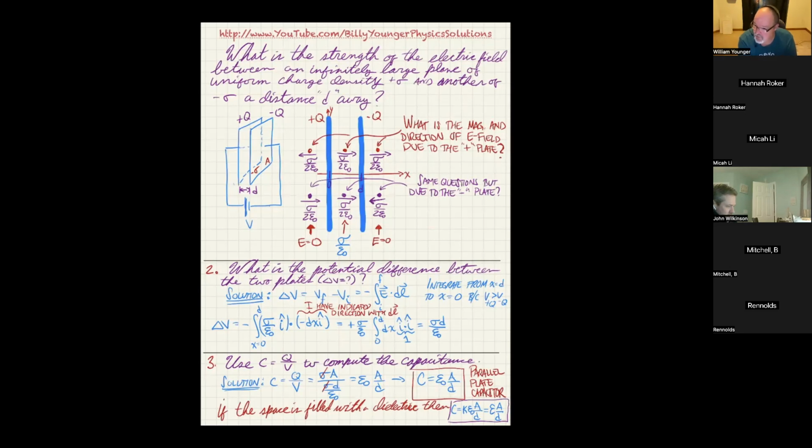Not only that, you've given it a structure where you can keep the two conductive plates from touching, because since you can see that the capacitance is epsilon 0 A over D, you really want the A to be large to get a large capacitance, and you want the D to be small to get a large capacitance. A being large is bad enough because these are things that fit inside of little radios or cell phones and stuff like that. But D being very small is also a problem because that brings the two plates so close together that lightning's even more likely to strike.